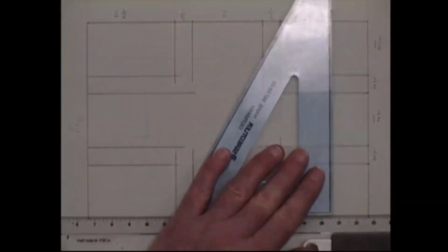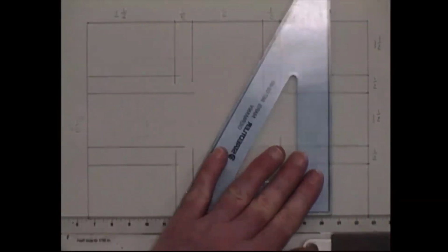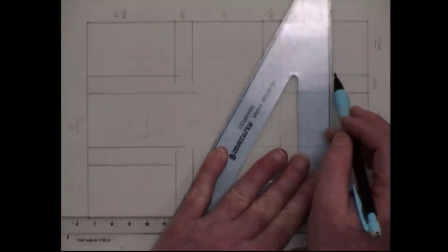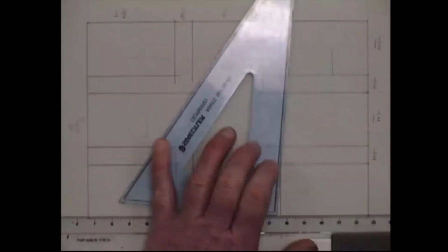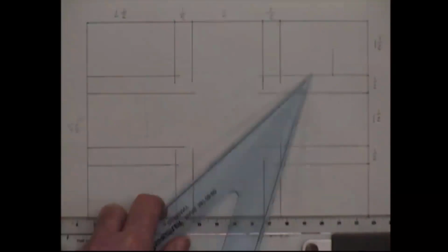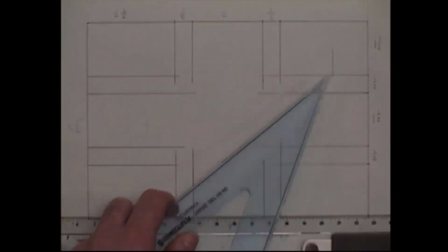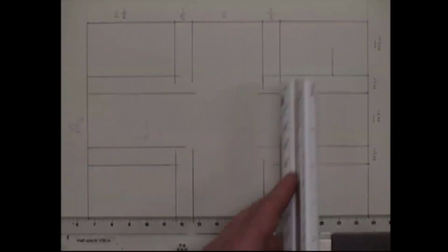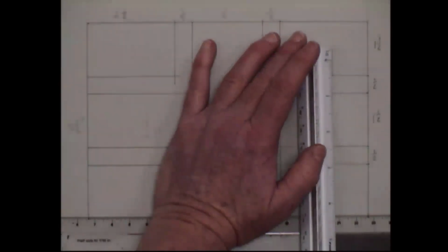We know that that vertical line is not going to be very tall there. It's going to be 5/8 of an inch, but I'm just going to go ahead and draw it about that much. Then I can put my scale up to it and make sure I'm getting actual 5/8 of an inch because I'm measuring along a straight line. If I tried to measure it without putting it up to a straight line, my scale could turn and I could actually have a different size than what I need.